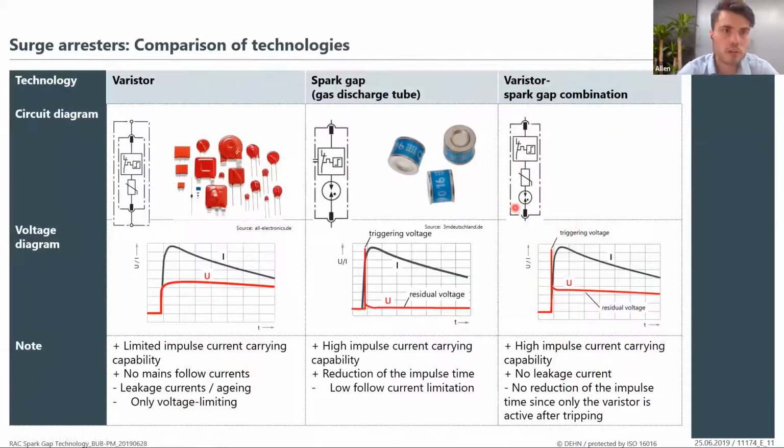So there are different types of technologies associated with surge protection devices. First of all, you get your varistor type surge protection devices, which are called voltage limiting surge protection devices. From the graph, you can see that a voltage limiting device actually limits the voltage to below a certain value. Where your spark gap switches the lightning current to ground, which can be seen by this small peak on the red graph over here, it reduces your residual voltage to nearly 0.